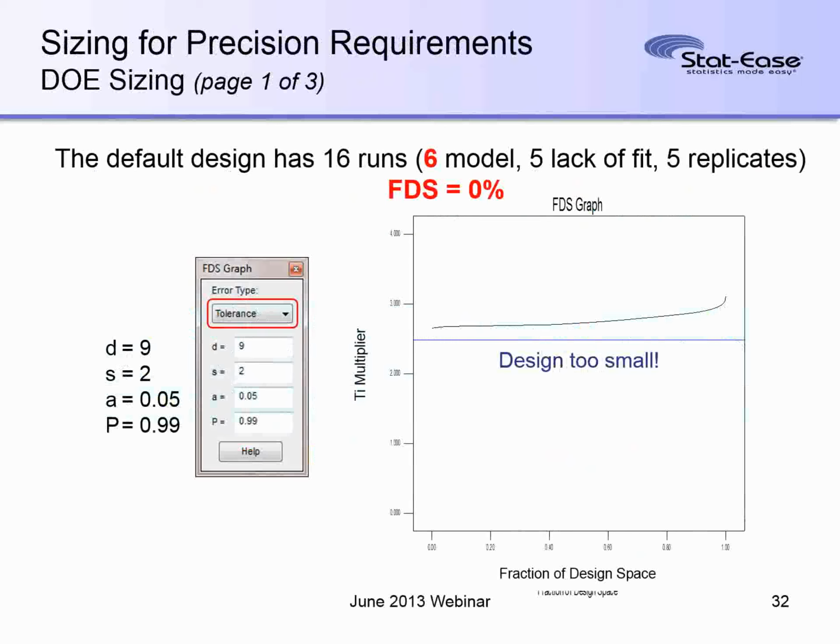The things you can do to fix that are manage your expectations and go with a bigger D. If this is our budget, we can't get this kind of tolerance, maybe we should go to 11 or 12. Is there some way to reduce the standard deviation? A better measurement system, better control of the noise sources.